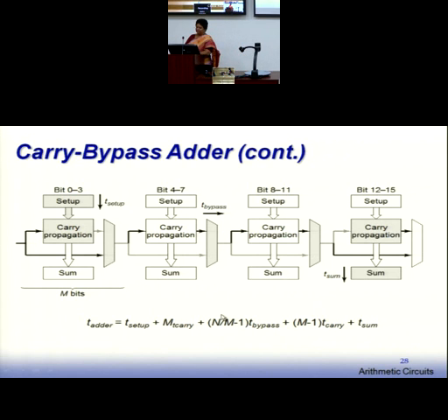So I will have (N by M minus 1) T bypass. What is this for? This is when you get this value. When you get this value, you are getting this path and then through this bypass, this carry over here is obtained. But the sum at the 16-bit, 15-bit position is not. I have to get the sum also. Now to get the sum at the 15th bit position, this C15 will not help you. It requires C14.